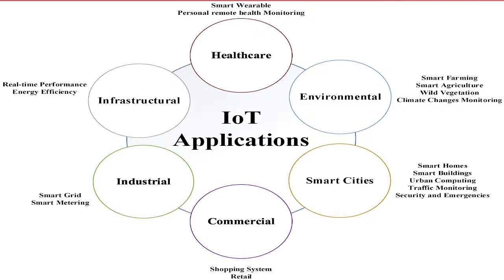How are they using it? Simply with object detection only, and also some magnets, IR sensors, ultrasonic sensors. For example, when you are entering a mall, like Phoenix mall, the automatic door opens and closes. How is it happening? There will be a PIR sensor, or an ultrasonic sensor, or an IR sensor. We can use these three sensors.